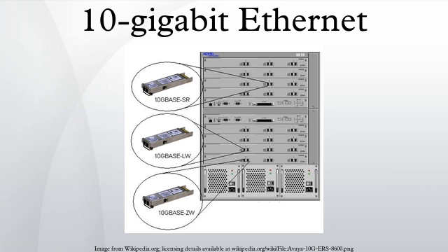SFP+ modules do only optical to electrical conversion, no clock and data recovery, putting a higher burden on the host's channel equalization. SFP+ modules share a common physical form factor with legacy SFP modules, allowing higher port density than XFP and the reuse of existing designs for 24 or 48 ports in a 19 inch rack width blade.